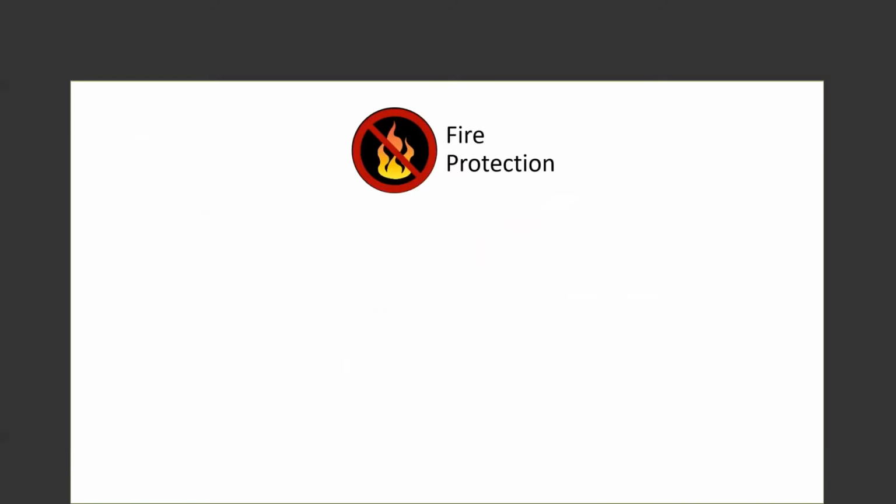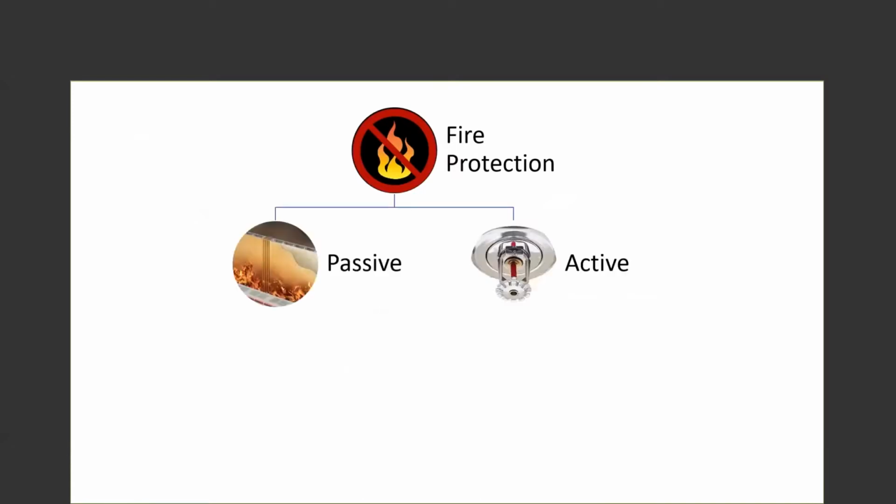How fire protection typically works is, as a lot of you may know, active and passive fire protection, as terms, are very well known. All equipment and systems which are designed into buildings that activate when they sense or see a fire are known as active fire protection measures or systems, like annunciators, smoke detectors, alarms, and anything that activates when there is a fire comes under the category of active fire protection system.